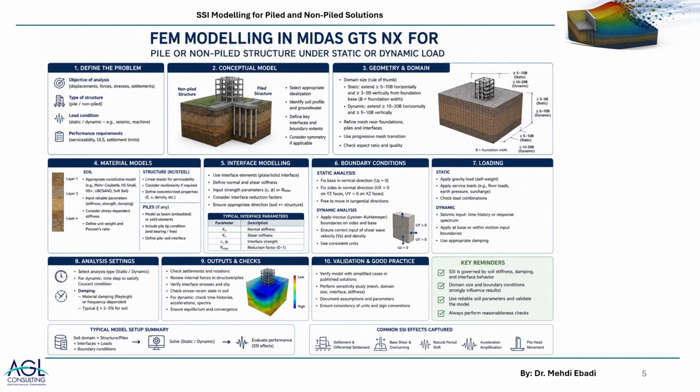If your boundaries are far enough from the model, assuming that it's static, it doesn't matter if you use fully fixed or rollers for the side boundaries. But if you are not sure that your boundaries are far enough, absolutely use rollers for the side boundaries. That's, again, a general note.